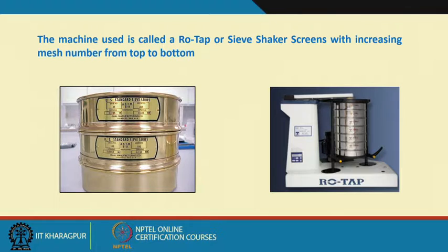So, what I will do? I will take another sieve, I will take again that 200 grams sample, and I will take a 40 micrometer sieve and we start doing hand sieving. And now, instead of taking out the particles which are retained on that, I will measure the weight of the particles which are finer than 40 micrometers aperture, and that again should not be more than 5% of my total population.